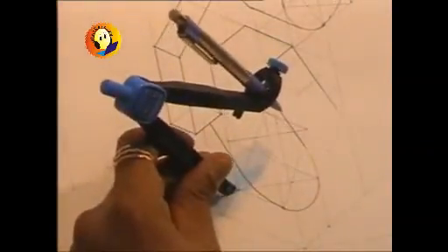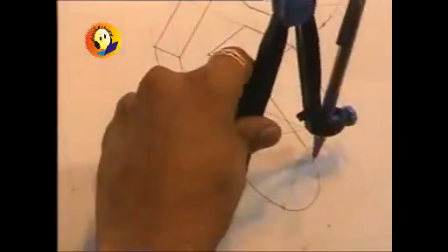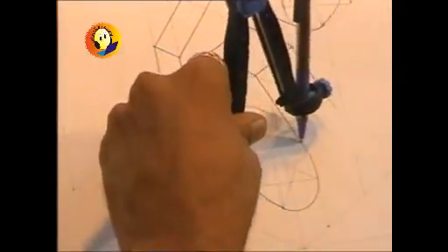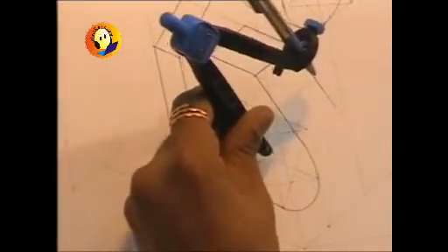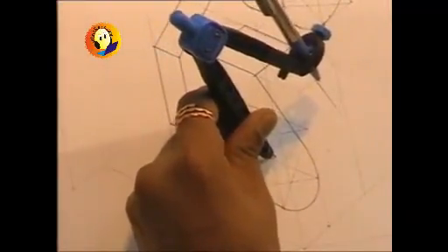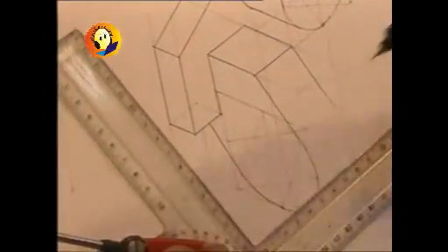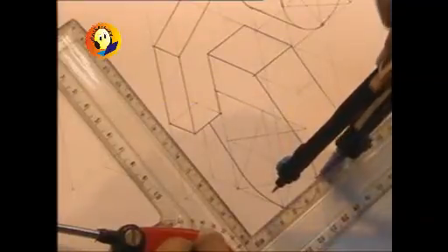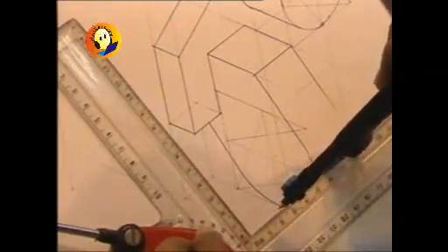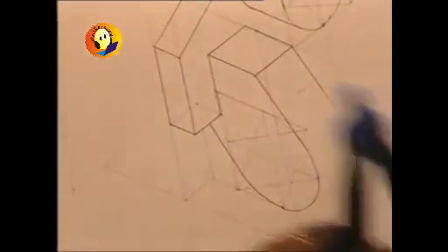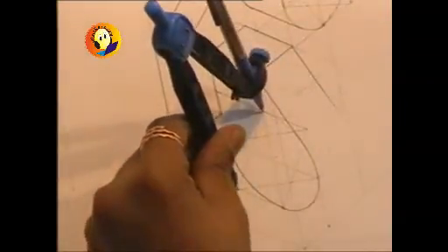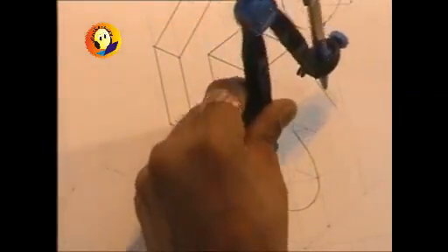Similarly from here you are required to darken only the part which is visible. Also I will be requiring this reference line here, up to which the arc should be drawn, and of course the common tangent line, because those positions will be the points up to which the arc should be shown.